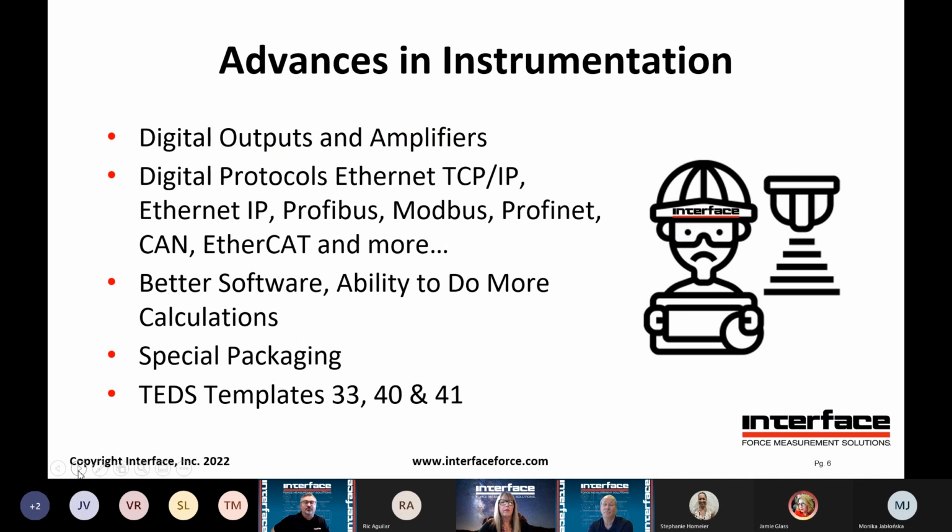So let's talk about digital outputs and amplifiers. There's a lot of different digital protocols: Ethernet TCP/IP, which is just your normal PC Ethernet type connection, Ethernet/IP, which is totally different and not to be confused, Profibus, Modbus, Profinet, CAN, EtherCAT, you name it.